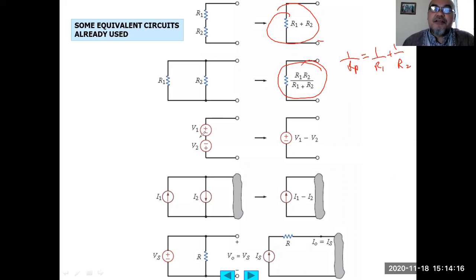So when we have two voltage sources in series like this, we can combine them basically into a single voltage source. So for example, if the overall terminal here, the upper part, is positive, we consider it more positive than the lower part, then the combined voltage source becomes V1 negative V2 here, because V2 is drawn with the upper part more negative, or less potential, compared to the bottom part. So that's why it is negative. So the resultant is V1 negative V2.